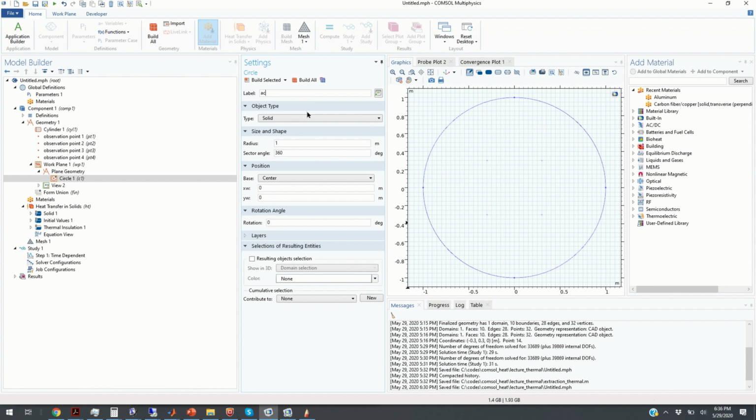We're going to call it actuator 1. Now, its position is going to be 0.5, 0.5, and the radius is going to be a small radius, let's say 0.02. Or let us increase this a little bit, 0.04. So here is our circle. So we're going to assume that basically microheaters are acting on this surface.